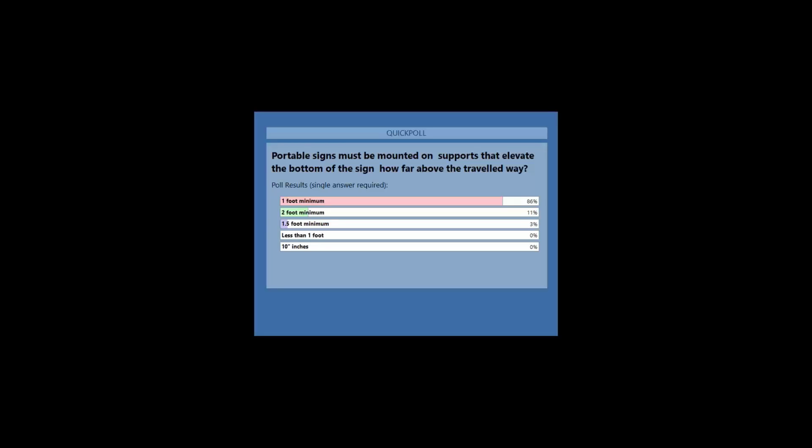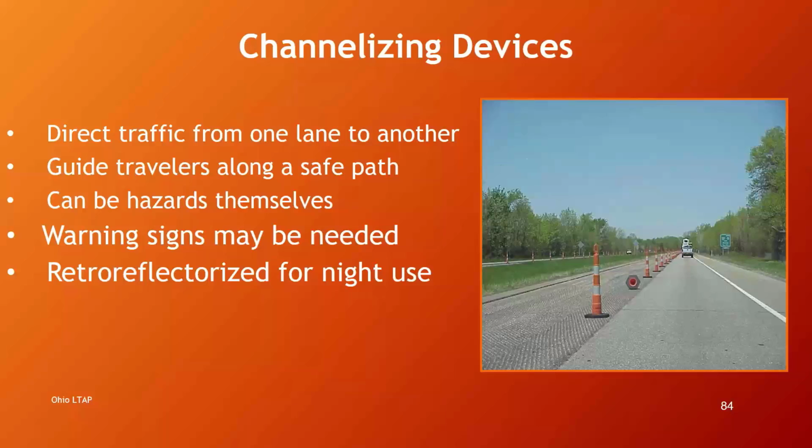A lot of studies, and you'll see in a lot of engineering drawings, they show a 3.5 foot height. When something is 3.5 foot above the edge of pavement, or the height of the pavement, drivers can read that message from quite a distance, and that's how they came up with that. All right, Ray, I closed those responses out, so it's all yours now.